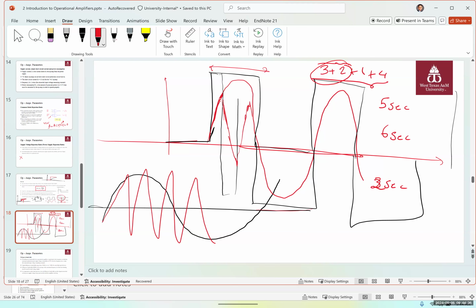That's exactly what happens to a signal. You're not giving enough time to the signal to fully respond to that input. So you're not going to have a full signal. You're going to have a distorted signal. You're not going to have the full solution. You're going to have a partial solution to the system. Okay. So instead of having a clean sinusoid in the output, you're going to have a triangle signal, for example, a distorted signal in the output.